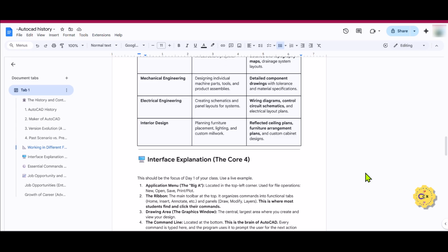I understand you know the things, but don't just name them. Try to read them in very detail, because when you work in the field, you need to apply them there, right? Bevel gears should be at 90 degrees to each other. Spur gears are parallel to each other. The only thing is that the PCD and the module of the gears have to match while they are engaging each other.